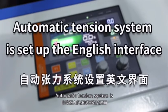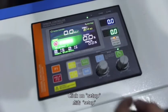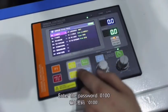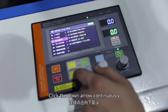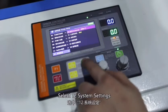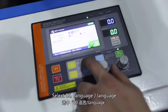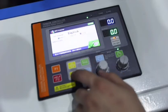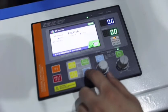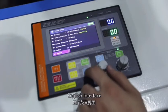Automatic tension system English interface setting. Click on Setup. Enter the password 0100. Click the down arrow continuously. Select 12 system setting. Select 00. Language. Select English. Click Exit to return. Setup is complete. Display the English interface.